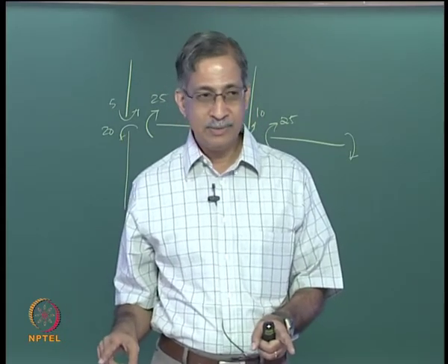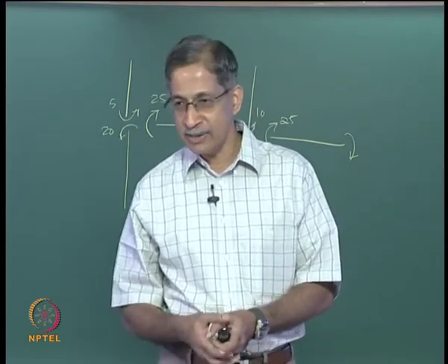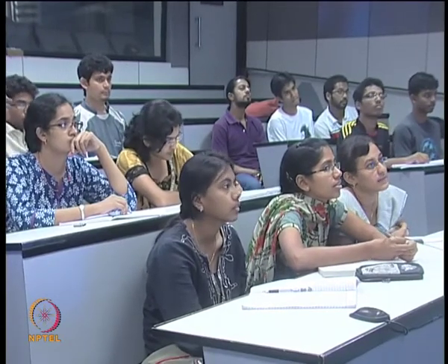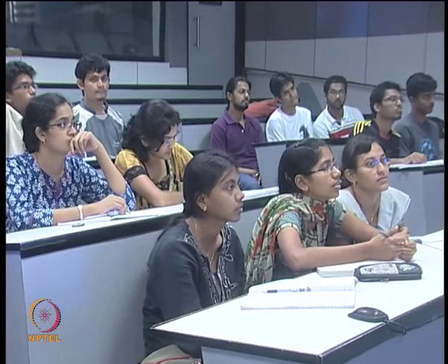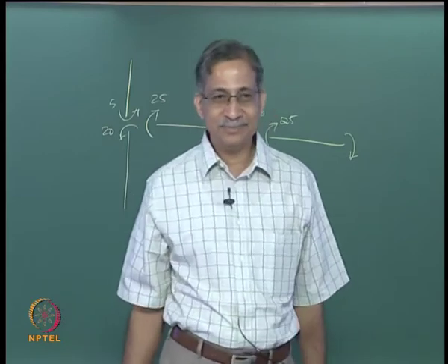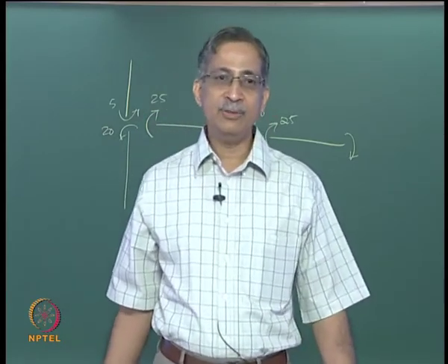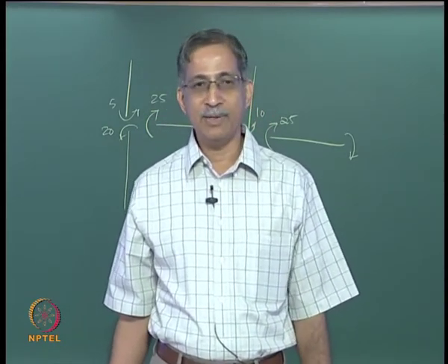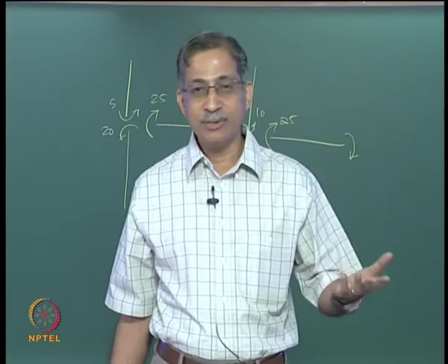Shear in which? Beam, because we have already got the shear in the columns. How do you get the shear force in the beam? Add the 2 end moments in the beam, divide by the span of the beam. So that is right, you guys are good, you can do this. So what do you get? 5 into 2 divided by 3 is 3.33. You got all the shear force in the top.